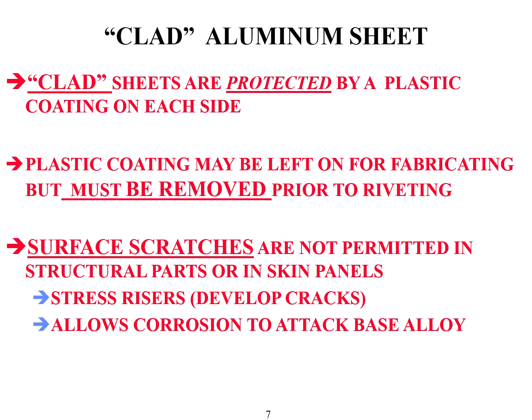More than once, I've had someone turn in a project, the plastic sheet was still in the stack up, and they've had to go back and drill it apart. So make sure to remove it, but we're going to try to keep it on as long as possible. Any scratches can very easily go through slightly over 2 thousandths of pure aluminum. So if you scratch, and you can see it, chances are it's scratched down to the core material. Not only could it develop a crack there, but it allows corrosion to get in and attack our base material.